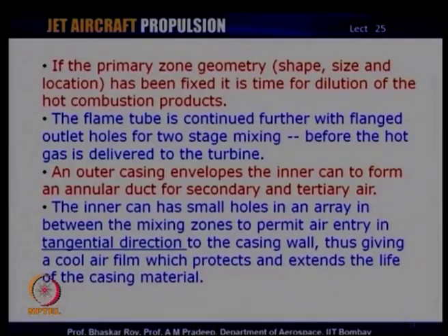The typical geometry of the vent holes, their positions and their sizes are to be designed into the flame tube, and they then create a proper mixing process inside those mixing zones. So, creation of those vent holes is extremely important, and it is the combustion chamber designer who creates those designed holes.